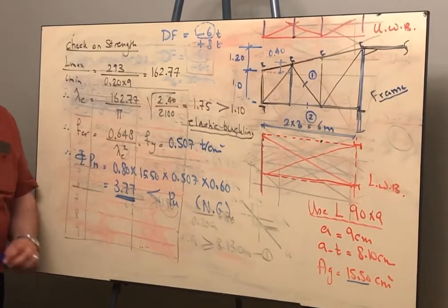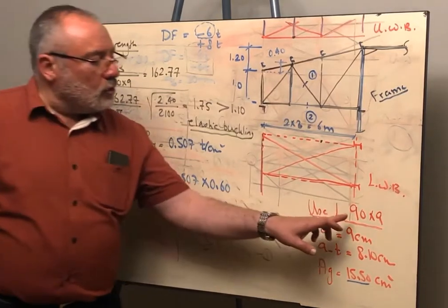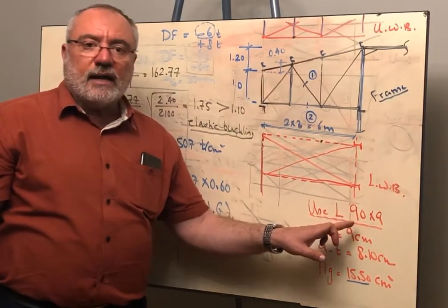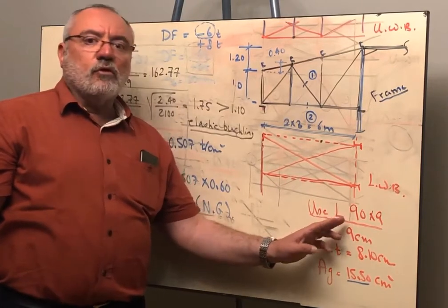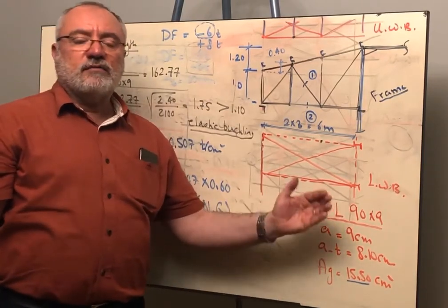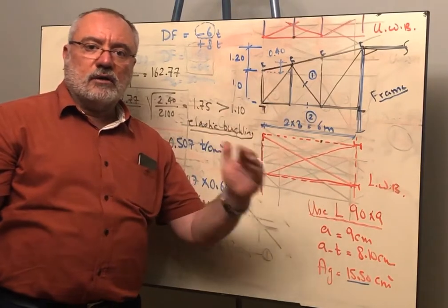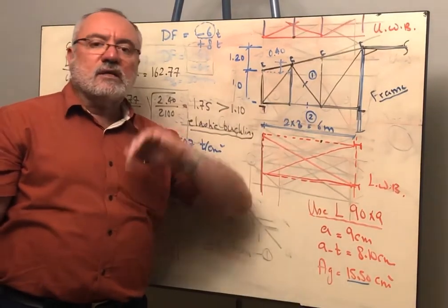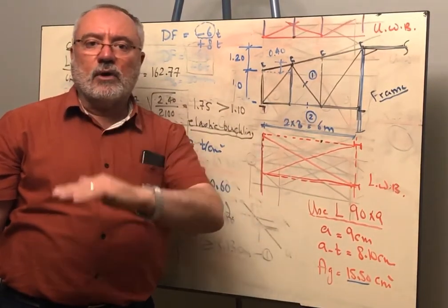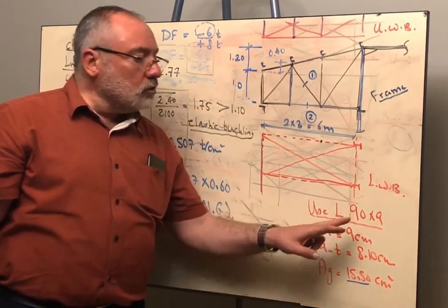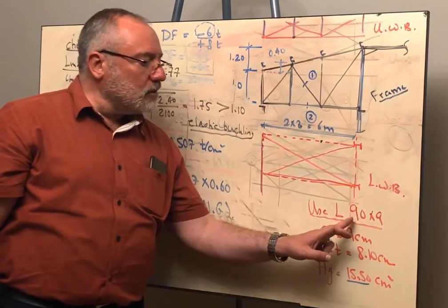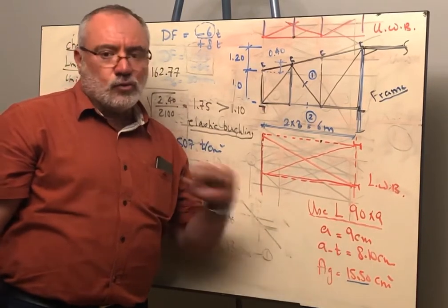What can we do? Now, you don't check for the angle for the other thickness, which is 11 millimeter, but you will have to go for the other family. The other family is 100 by 100 by 10, or the family that follows, which is 110 by 110 by 10. So you don't increase the thickness of the angle, but you increase the angle leg as well.